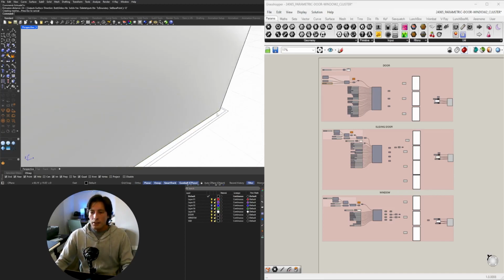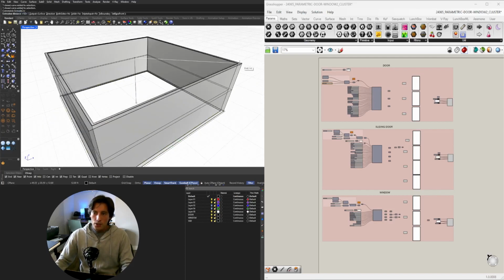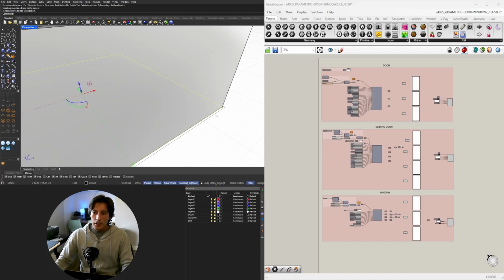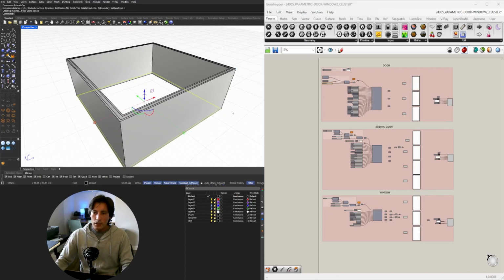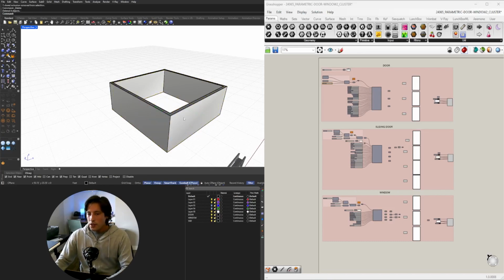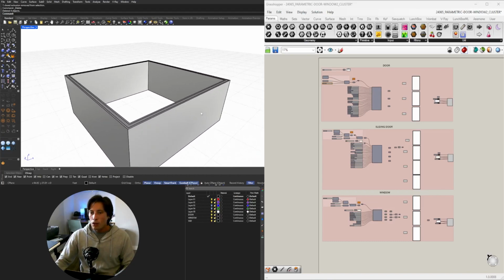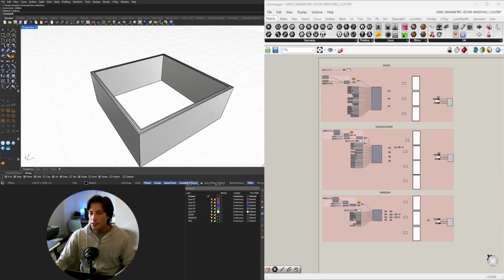And do the same thing between this one and the wall. So extrude curve, making sure that it says solid. So we're creating our base geometry, which is the wall, interior, and exterior materials. The reason why I made this 0.5 and these two 0.25 is because that makes the outside wall 1 foot, and that makes it easier for us to change it here. Of course, depending on whatever size walls and assembly you have, you would actually vary this number.